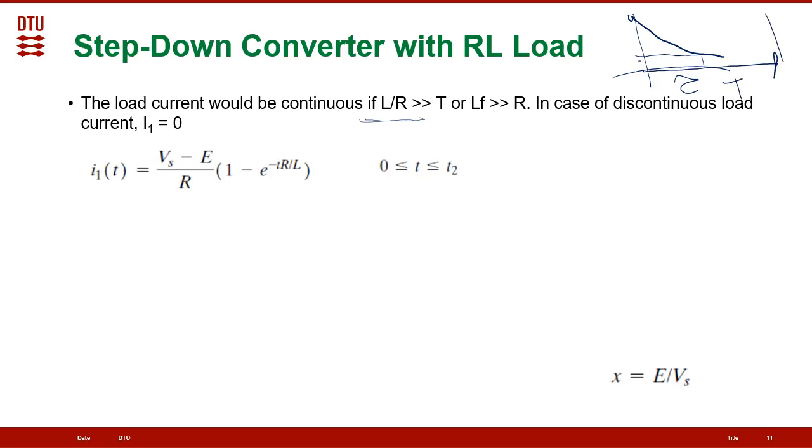So here you can see that if this happens, then the current can reach 0 during one cycle. So what we need to do is select tau to be much bigger, so that the inductor takes a longer time to be discharged. Again, here we can define the time required for the current to reach 0.